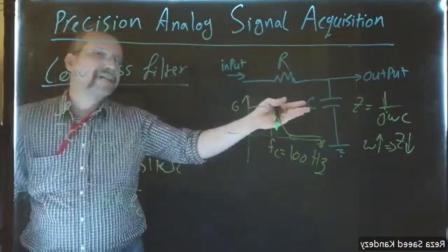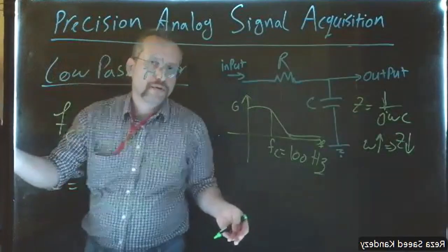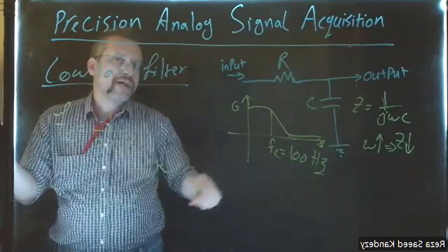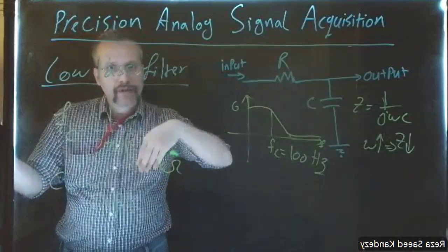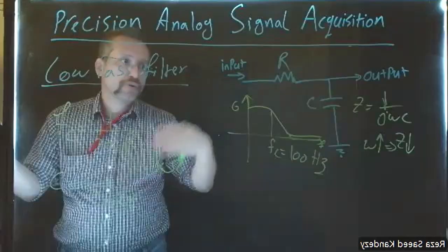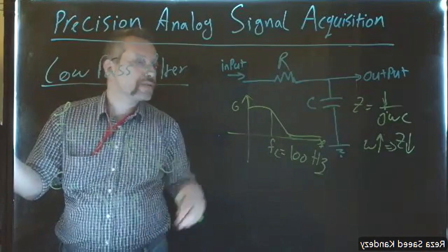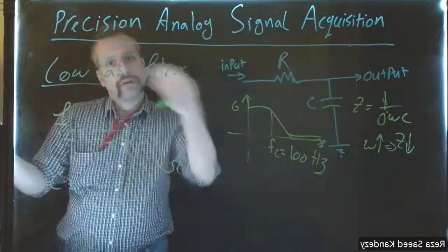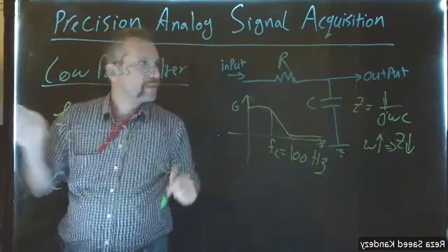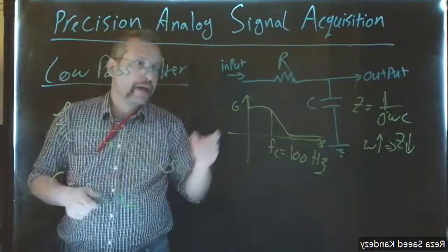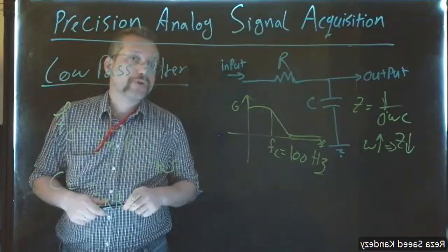So that is it. And you already know, if you want to use an active filter, it would have a strong output, but as I said, it is costly, and you have to provide a VCC because you're using an op amp and you have to supply energy for those active devices. You can use our discussion in the previous lab to design the active filter if you want. Okay, so let's go to the lab and implement this RC first order low pass filter and see if it works or not.